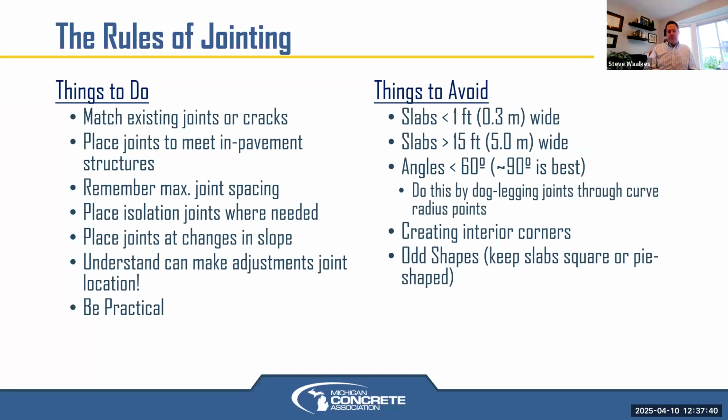And MDOT does use them for almost all their paving at all transverse joints, in the lanes at least, not usually in the shoulders. But the baskets themselves that those dowels are tack welded into to hold them in place during the paving operation, those baskets are still the plain black regular steel.